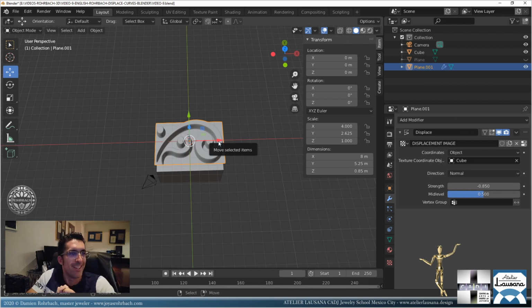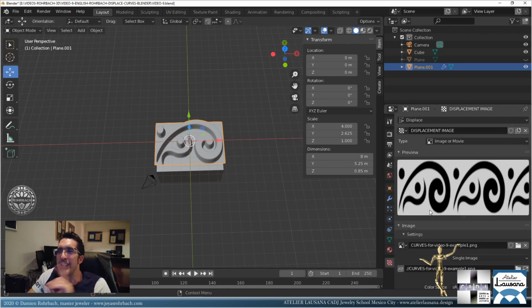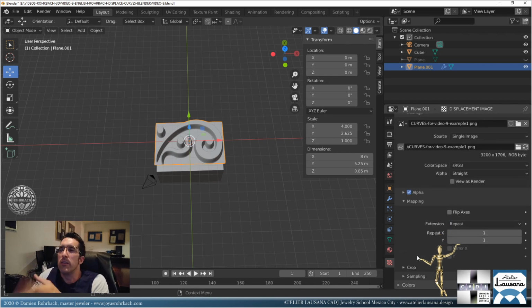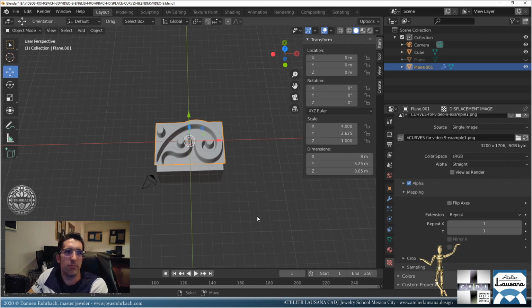Okay. And if it fails, which, like I already said, is almost every time, you need to know how to place and size the displacement texture, because you shouldn't try to change anything else, the mapping, all of that. In this occasion, you can do some things for placement and size from the texture parameters, but don't do it. Well, for beginners, just don't do it. It's going to trash your texture for sure. All right, so we're done with that.